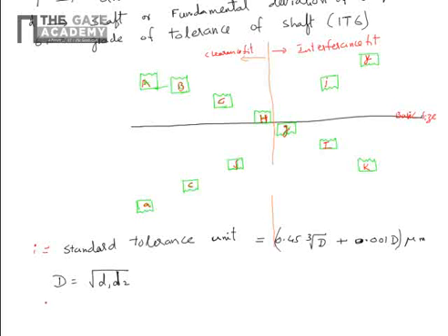That's about D. And suppose for example hole tolerance in the same problem equals IT7, which from the design book is 16i. So 16 into whatever value you get for i, you have to calculate and substitute here.